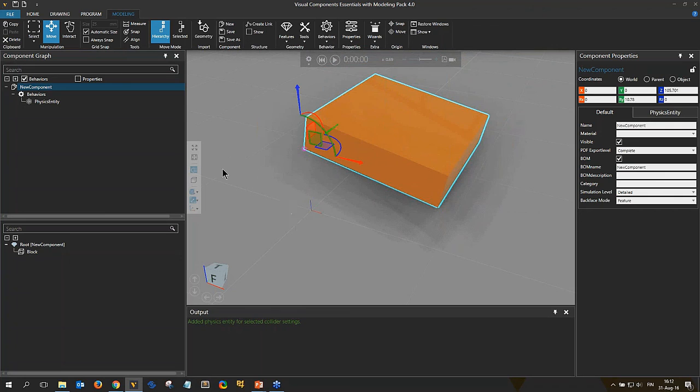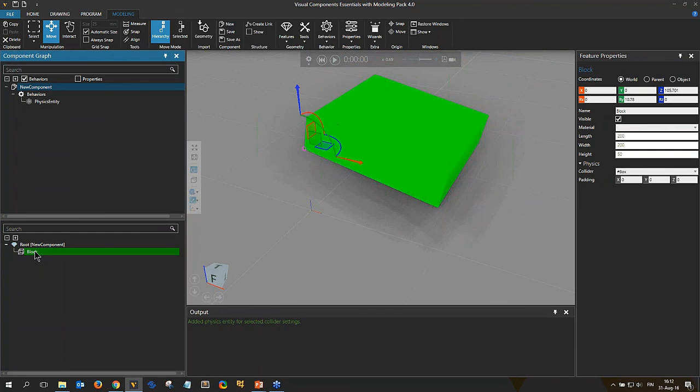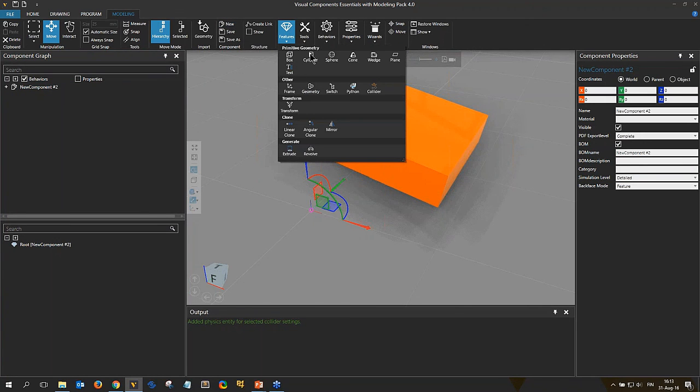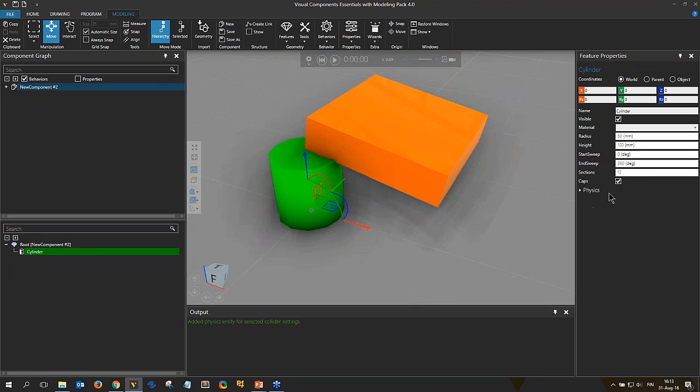And that box selection means that whatever your shape of that feature is, it will only put in physics calculation the bounding volume shape. So it will be very lightweight calculation. So even if you have a very heavy model and you put that in box mode there, you would get fast calculation, but the accuracy is not very good. And we can see that if we now create a new component, this time new feature, cylinder.